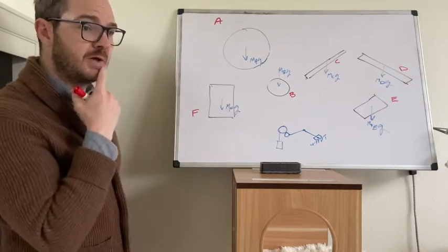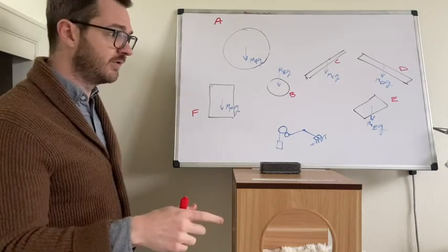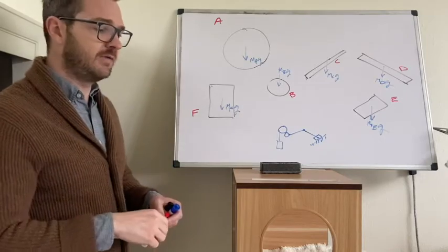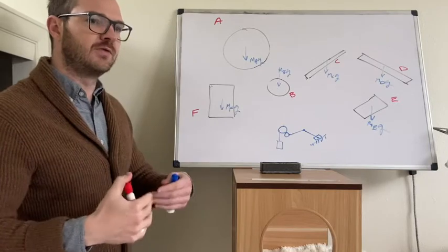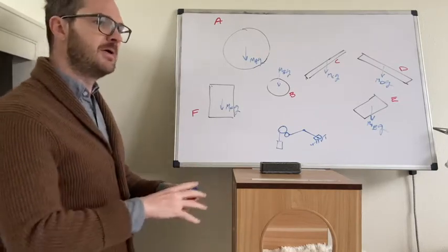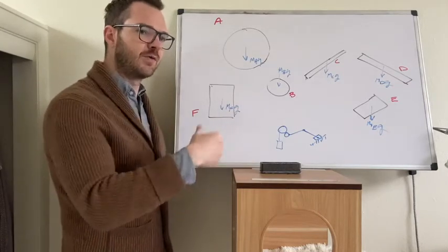Next, what are some other easy ones? Well, we know that there's going to be reaction forces at all of the joints. Anytime you have a joint, that joint provides some kind of constraint on the system. It takes away some local motion. There needs to be a reaction force on the diagram enforcing that constraint.